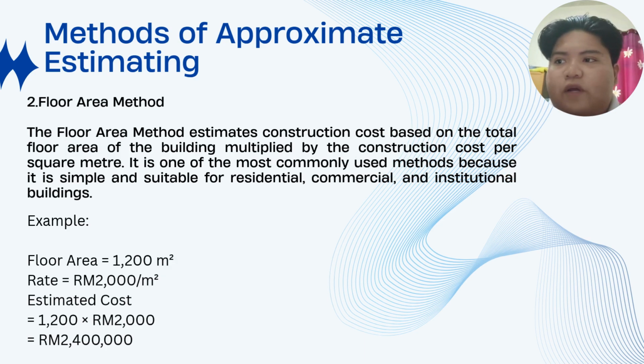Next, floor area method. The floor area method estimates construction cost based on the total floor area of the building multiplied by the construction cost per square meter. It is one of the most commonly used methods because it is simple and suitable for residential, commercial, and institutional buildings.